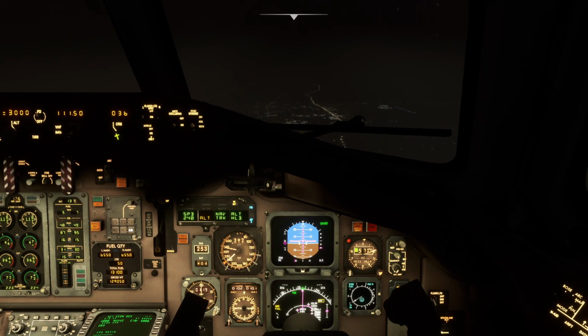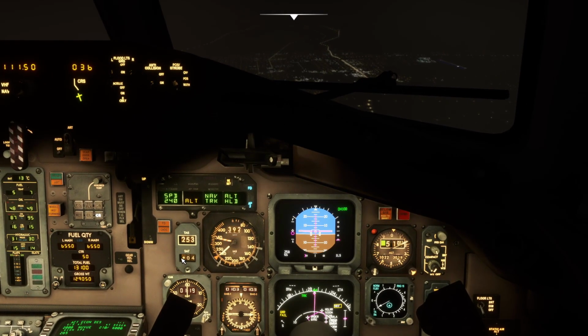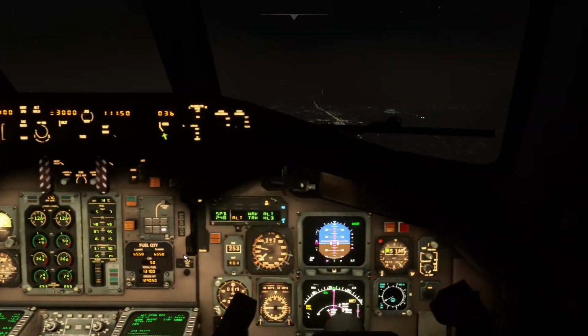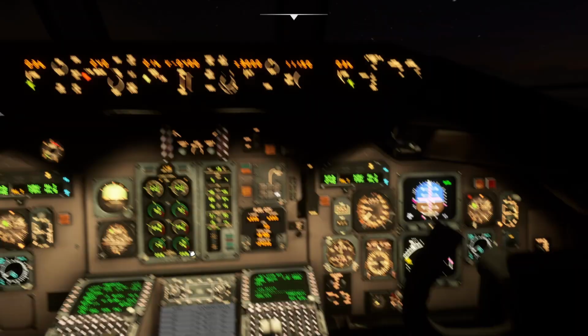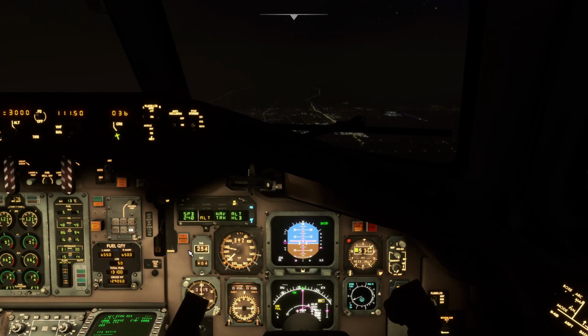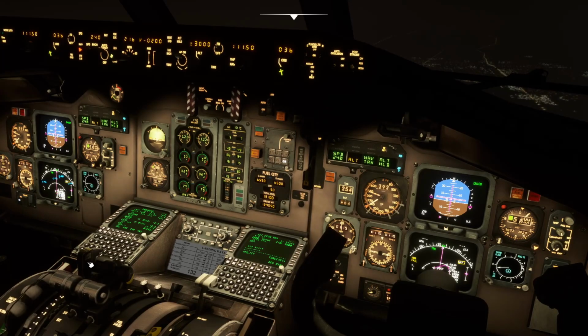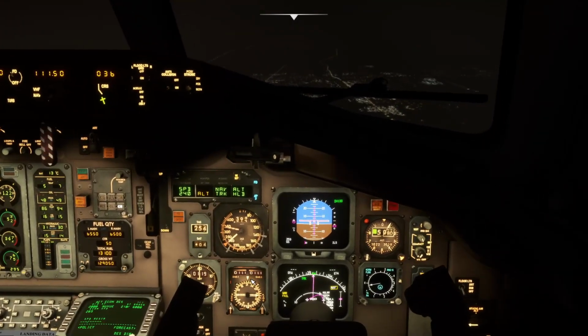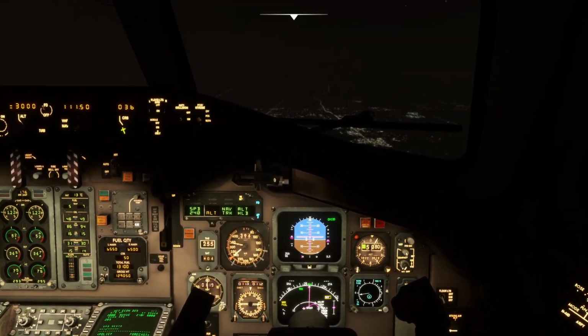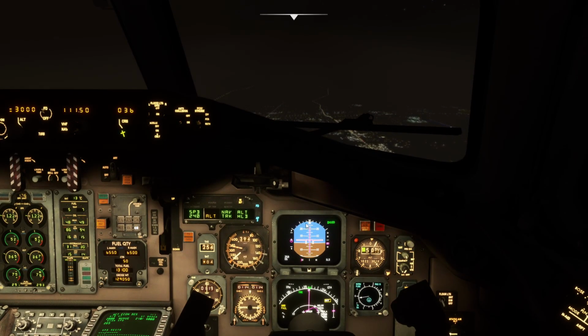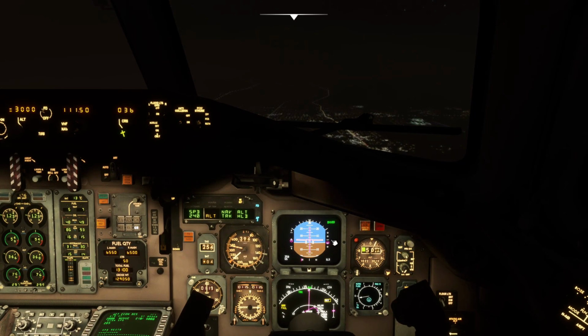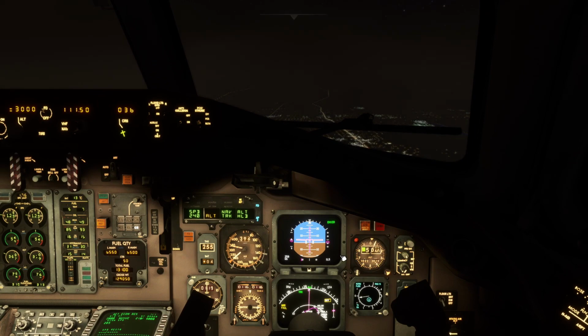Have a good night. The temperature gauge on this obviously is right here. It's reading plus 4, kind of icing conditions, but it's more or less clear, so I'll keep the anti-ice off for now. Very good, so we're reading 11 DME. So, we're good to make the base turn now. Obviously, you can see the glide slope's coming in from the other way around.